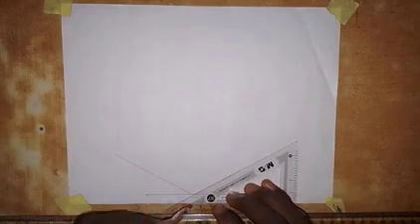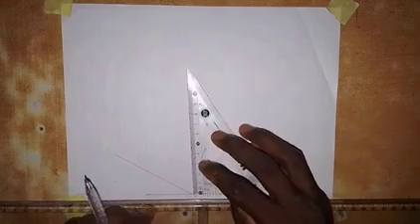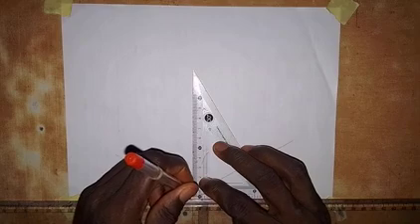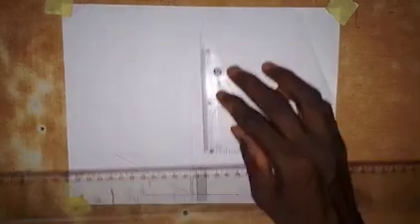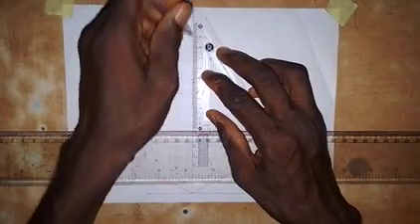Then I will take my 30-degree set square. Here I'm going to draw a line in this direction, and I will also draw a line in this direction. Alright, I want the front to face this side. Then I'm going to draw a vertical line. So the vertical line goes like this. Then I will also take it up because the total height is 140. So I will draw like this.